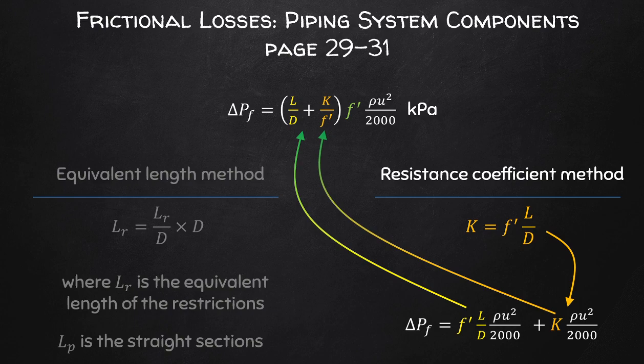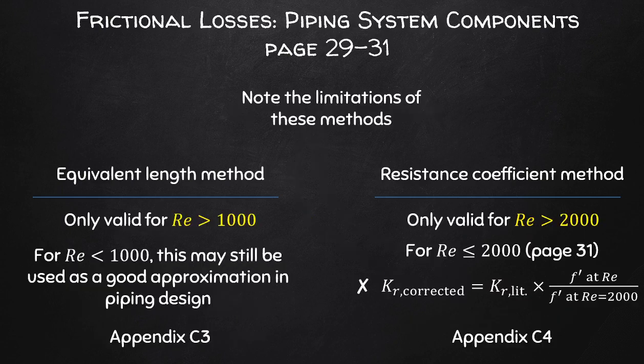We multiply this by F prime and obviously the diameter, which I've left out here, oopsie, but I'll get onto this now. So just some restrictions that we must keep in mind. Keep in mind that there are limits that apply to making use of these correlations, and also, if you are deep within the realms of laminar flow, you may need to adjust these correlations.